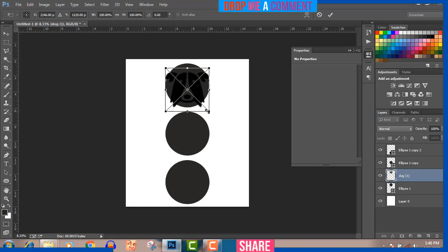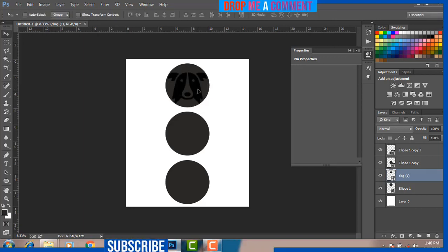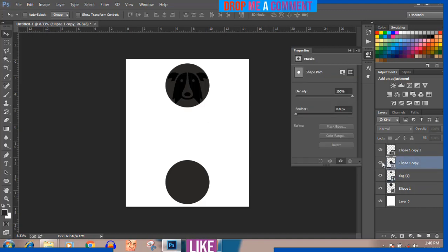Remember the way I told you to reduce: hover your mouse over this edge and press down 3 buttons, your Alt key, Shift key, and your left mouse click button, and just drag. So now we just left click and drag with our mouse to make sure that it is in the middle. Press enter. We'll come back to change the colors, so just leave that for later. So now you click on copy to, which is this one. If I click on this, you know that's copy to.